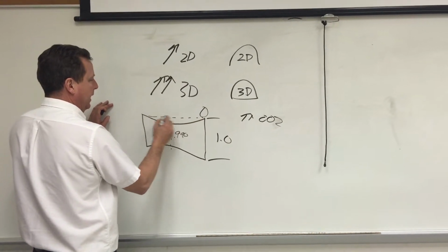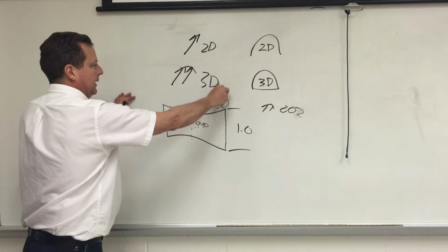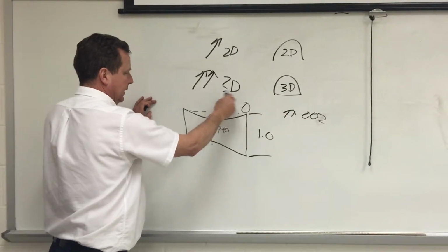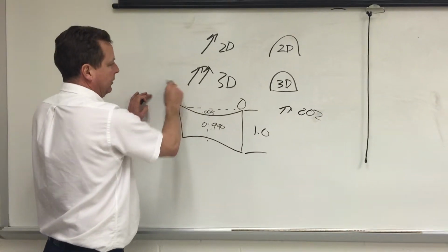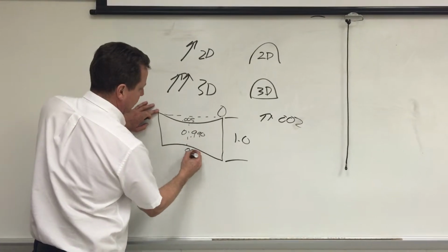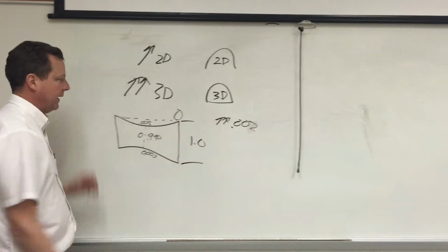Well, I'm going to have a 5 thousandths diameter gap here that has to be included as I move my dial indicator. It's going to fall 5 thousandths in this, and then go back up to 0 here, say, and it will be no good to the total runout tolerance of 2 thousandths.